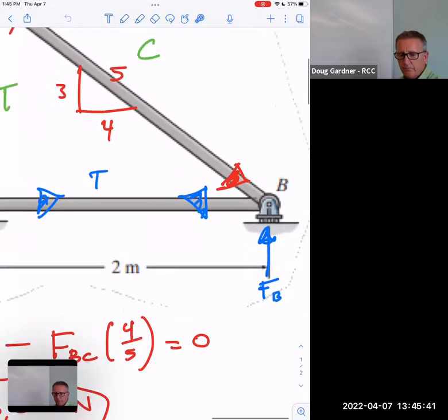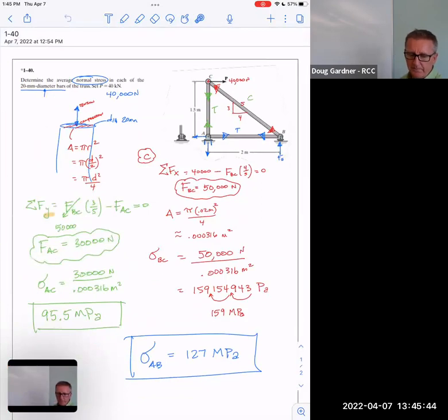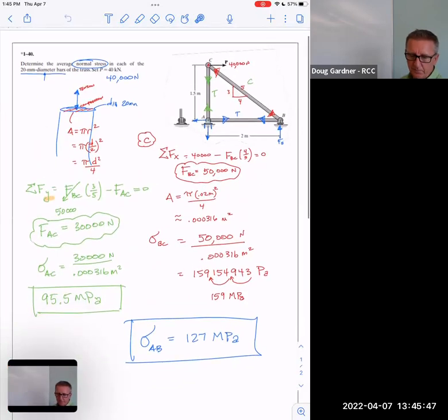Can you give me the normal stress of that one? Or 127? And it asks for the average, so we just average all these, right? Now why does it keep saying average? Why does it say average normal stress? Well, that's just because, as I said before, if I put weight on top of this right here, and I got 200 pounds of dirt pushing down on this right now, is it averaged over the whole thing? Is this table able to take this and work it all the way out to the side so this is doing the job too? Or is this actually going to puncture right through here?